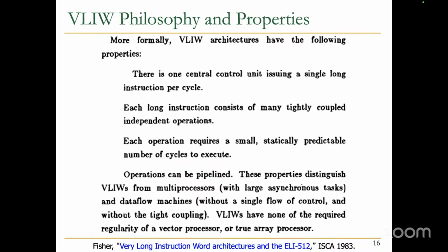For example, I'll take a multiply instruction. Does a multiply instruction always take n cycles? Let's say n is 8 cycles, I just picked. Basically, the answer is it depends. Why? Because if you're multiplying by 0, you can have a shortcut in the circuit that says, oh, the answer is 0 because one of the operands is 0. You could do it in 1 cycle with an equality checker. So sometimes a multiply takes 1 cycle, sometimes a multiply takes 8 cycles, depending on the data value.